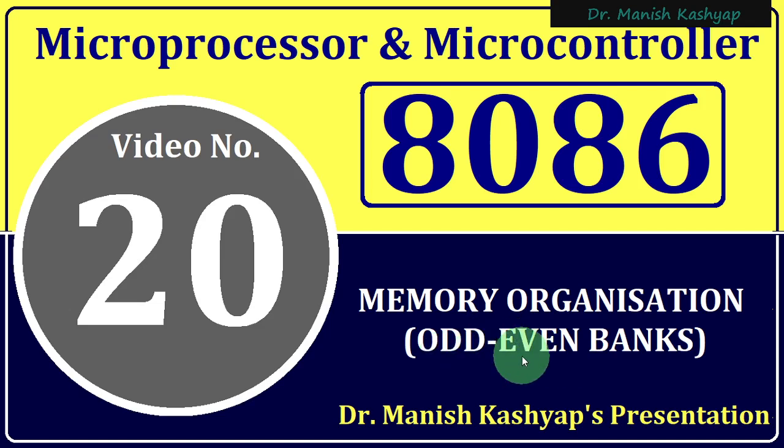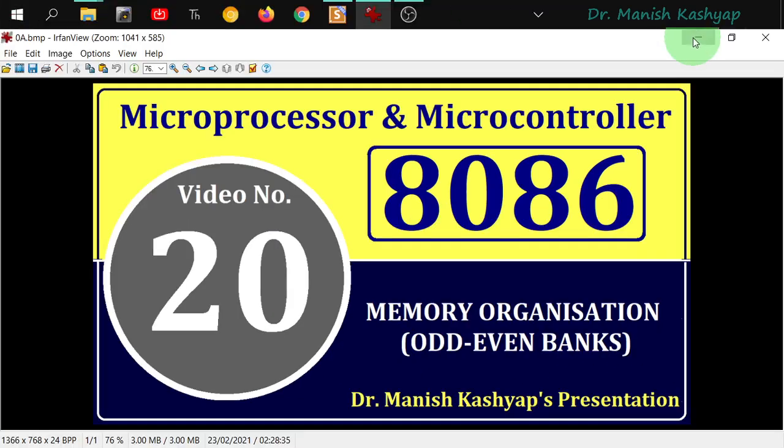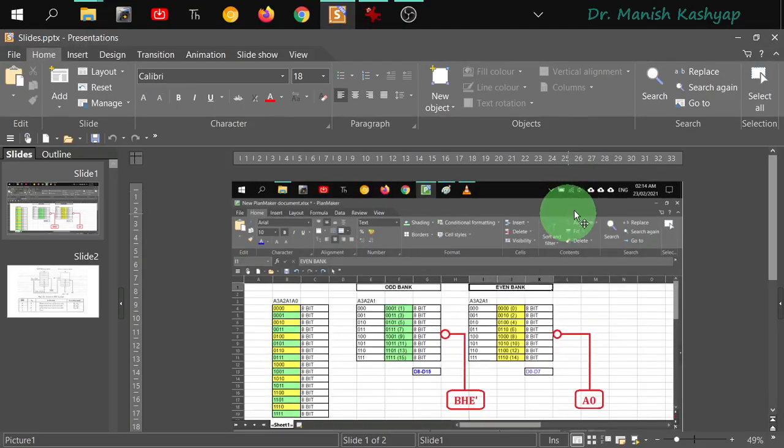We will see all those issues, but the primary advantage of using odd and even memory banks is that, since 8086 is a 16-bit microprocessor, if we want to write a word, that is 16-bit data, inside the memory, then definitely we have to access two consecutive memory locations because every memory location is of 1 byte only. So if you want to write 2 bytes in one machine cycle, then this odd-even memory bank segregation will help us. That's what this video is all about. Let me quickly take you to the slides.